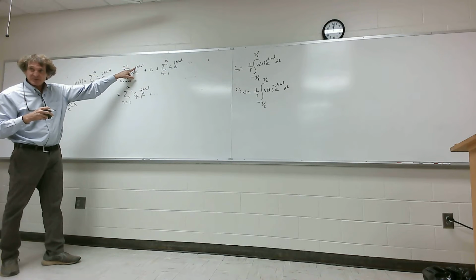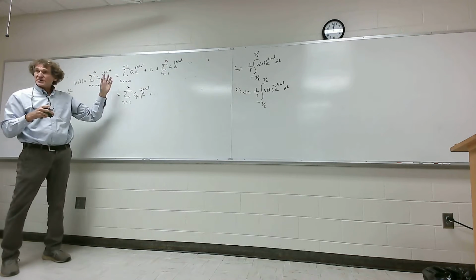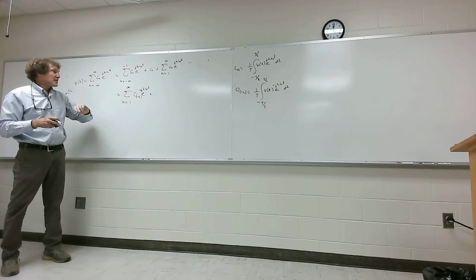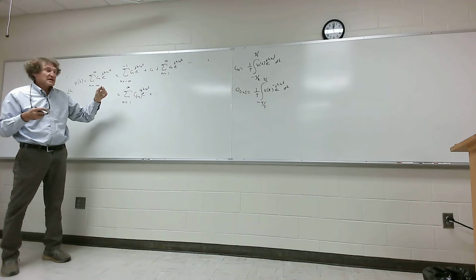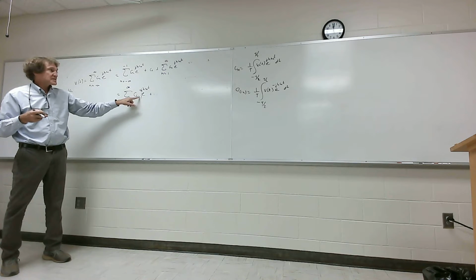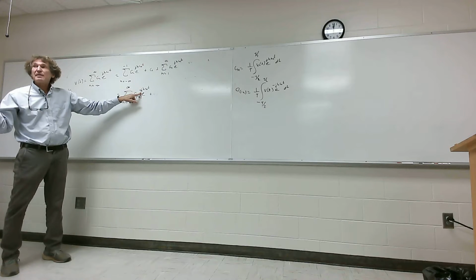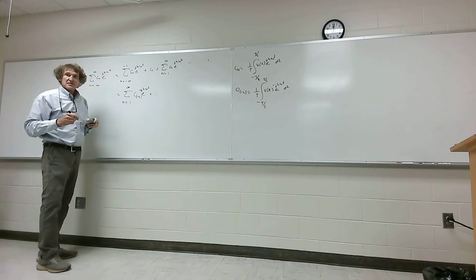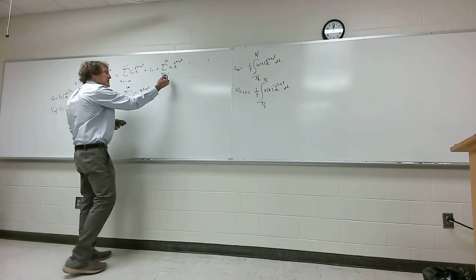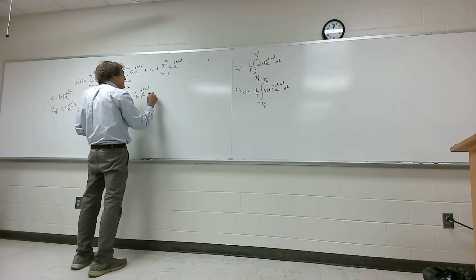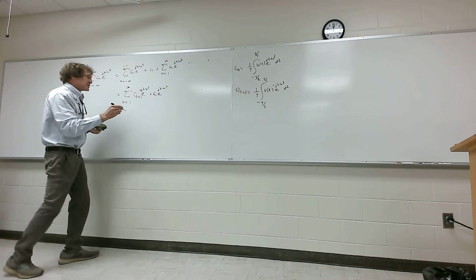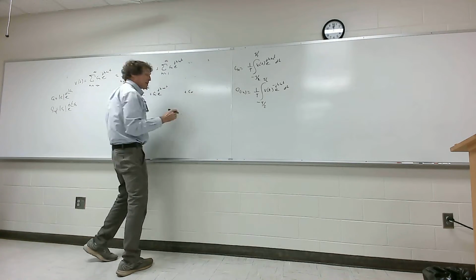It's the same thing. Just take a good look and convince yourself. I mean, do y'all see that right there, class? If you go from n equals minus infinity to minus 1, if I go from plus 1 to infinity, I can put a C of minus n there and a minus there. Y'all follow me? It's the same exact mathematical statement. Now I take that, and because I'm counting positive from 1 to infinity, I can add that right here. And say that's C of n e to the j n omega naught t plus C0 out here. Y'all with me?